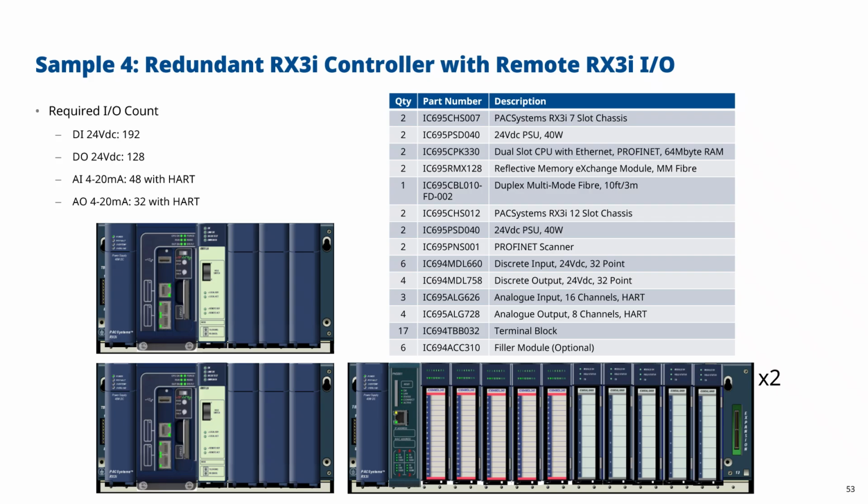There's not too much savings we can do in terms of the CPU, but maybe if the customer doesn't need that one scan failover, they could move to a CPE 400 edge controller solution. Alternatively, for better control on the CPU side, you might add the additional RMX modules and add a PROFINET controller, but that would be pushing the price upwards rather than bringing it down. So there's certainly optimizations on the I/O side. We've already optimized on the CPU side. But again, quite a nice clean solution.